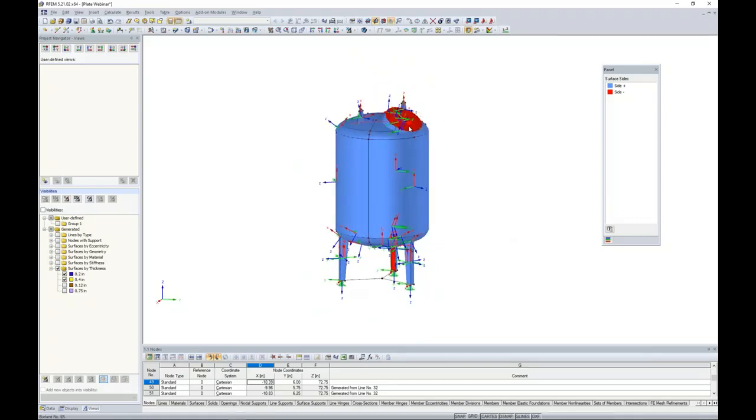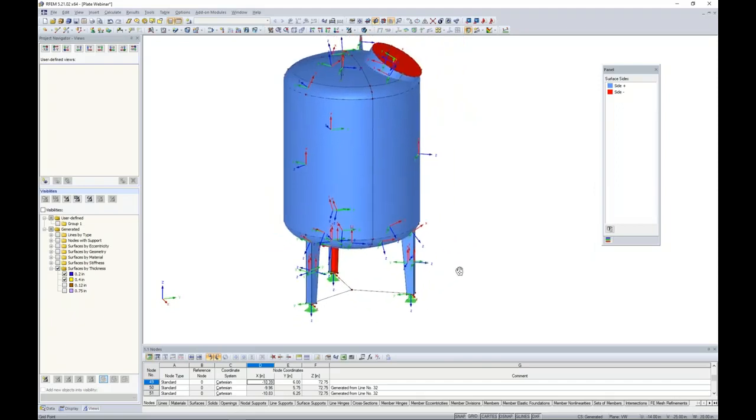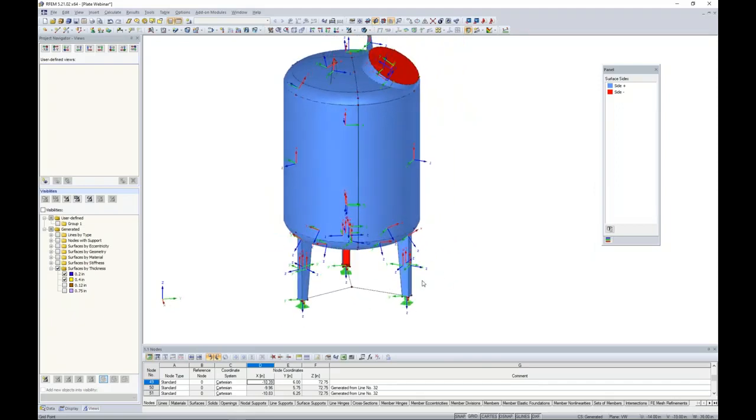We do have this rigid surface here. I guess technically we could reverse the orientation for that, but I'm not so concerned with loading the rigid surface or results, so not so important. So definitely something that you want to pay careful attention to before you get into loading. All right, so right-clicking, turning off the local axis system.